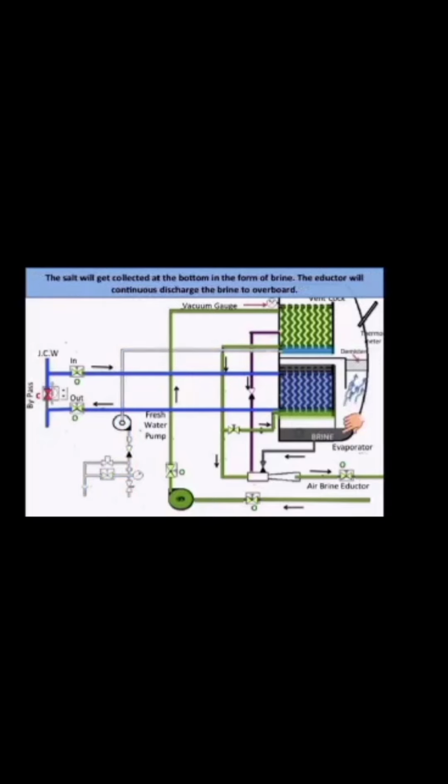The salt will get collected at the bottom in the form of brine. The eductor will continuously discharge the brine overboard. Start the freshwater distillate pump.